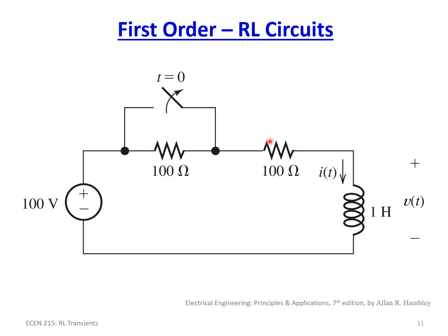And then when we open the switch, we end up with a 200 ohm circuit and an inductor. So following through, we end up with that K2 factor as initial current. In this case, it's 1 amp because of the initial circuit. So you end up with 1 amp minus Vs over R. Well, in this case, Vs over R is the circuit configuration at time equal to 0. So R is now going to be 200 ohms. So this here would be 1 amp minus 100 volts divided by 200 ohms, which is now half an amp. So K2 is going to be 1 minus a half, or a half.